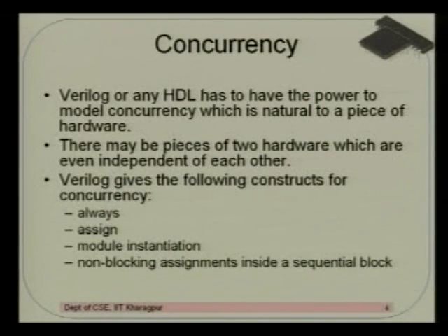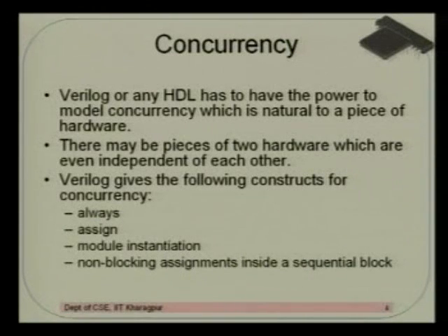Although I know that many of us may not know what the Verilog language is, the question is, where is Verilog different from normal languages like C? The thing which I will highlight is this feature of concurrency. Concurrency is an important feature that I require to express any piece of hardware. Why? Because think of a normal breadboard design. All of us have done breadboard designs in our labs, right? In our breadboard design, we have a piece of design with various blocks which are functioning concurrently, that is, they are working in parallel.